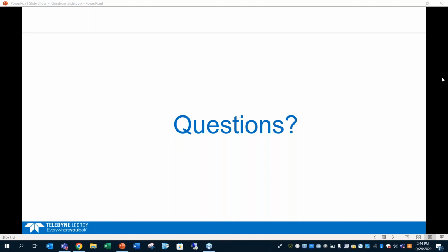The next question is, sometimes we can see in the trace a lot of loss of sync indications during the link training phase, even close to completing the link training. What would this indicate? Josh? Yeah, a loss of sync means that, as seen from the analyzer anyway, we lost sync, that the signal has basically disappeared, or is so bad that we can't make an interpretation of it at that point.